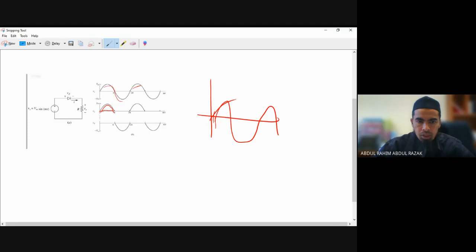Once you have a flowing voltage throughout the diode and also throughout your load, the current also will ramp up. It ramps up here, and it's blocked here. Same goes to here. We can measure the current as well. On the reverse bias there will be no current because it blocks. There will be only current that flows on the positive cycles.